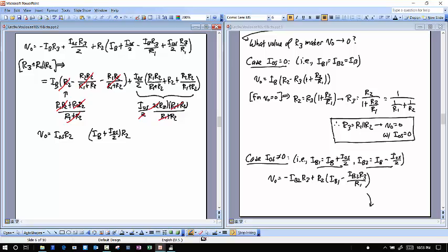And so we want to compare the two of these. Well, IOS here is just 10 nanoamps, whereas this IB was 100 nanoamps. And then this IOS over 2 is about 5 nanoamps. Okay, but clearly this on the right is much bigger than what I have on the left, so it still helps.